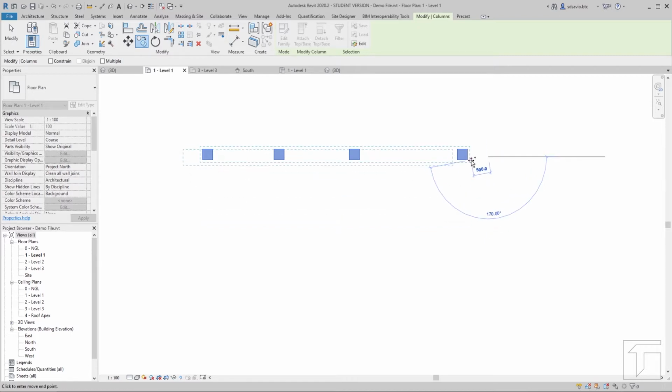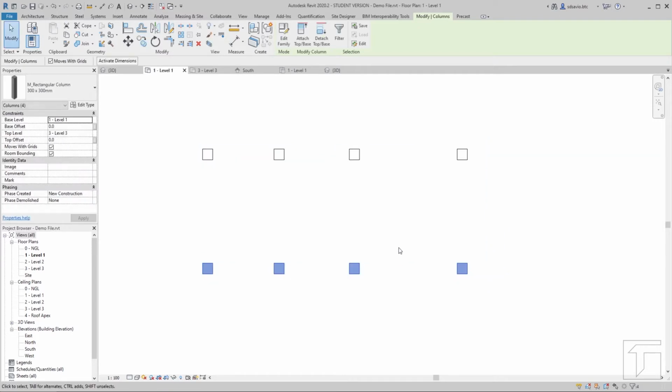So this is actually the origin spot. Also, it gives me an angle. Now since I want to copy it straight down, I'll make sure that the position of my mouse is also going on a 90 degree, as you can see on the guide there. Okay, so let me just place there. Again, I'll not be strict with the distance first for this roughing in of columns. So let me click to finally place the copied columns there.